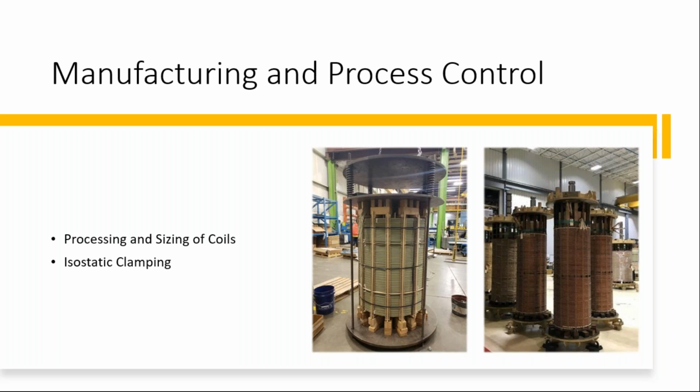So we know the coil has reached to this point, and once the job is finally dried in vapor phase and goes into the tank, it will have the same tolerance. By keeping tight tolerance on the height, we are ensuring the coils, HV, LV, and regulation winding, all of them have a center point which is not shifted. That will help to maintain the short circuit forces up to the design level. If they are unbalanced, those forces could be way more than design has calculated.